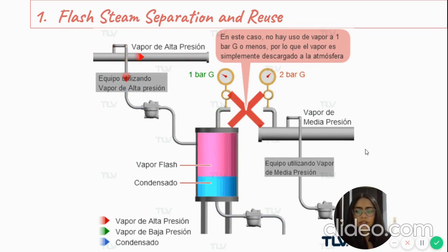However, a flash steam recovery system results in a great amount of back pressure. Care must be taken to maintain the necessary pressure difference at the traps so that the steam traps can continue to operate. In addition, there must also be a real need for the use of the low or medium pressure steam provided by the flash tank. Sometimes the pressure of the recovered flash steam is below the minimum pressure or temperature required for use.